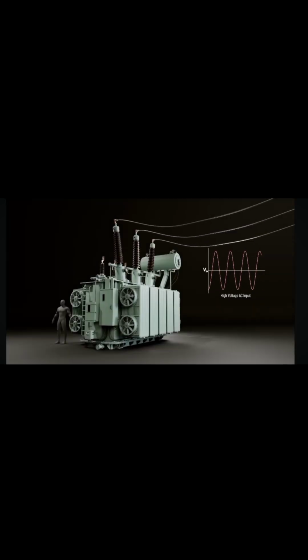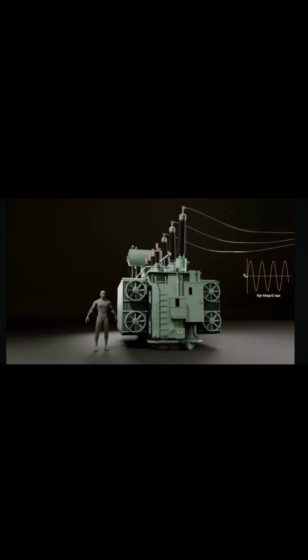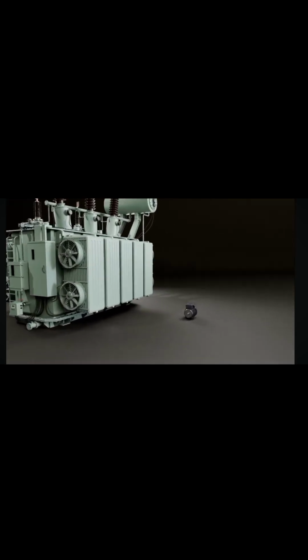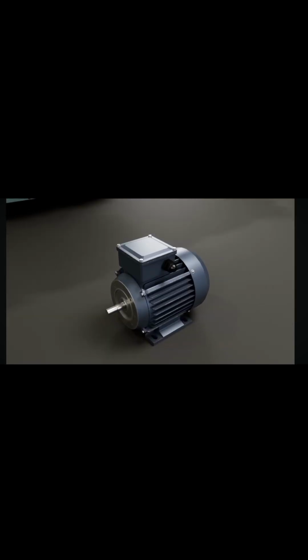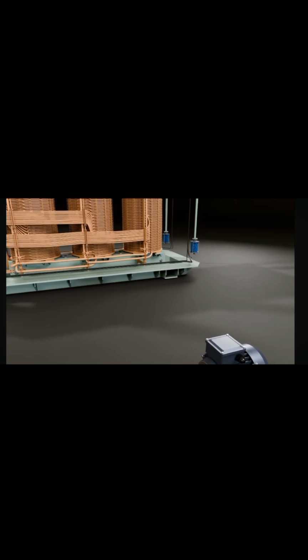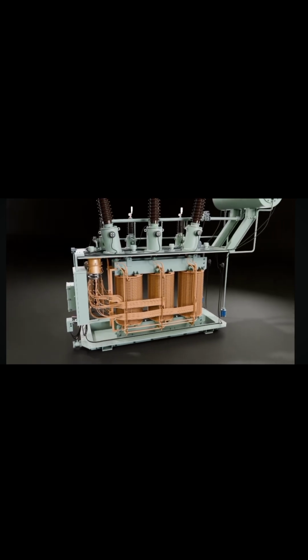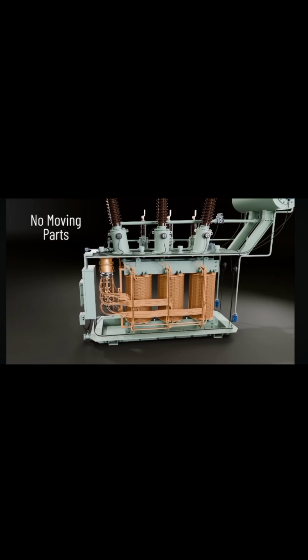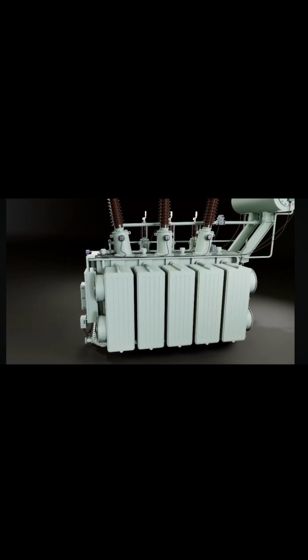A transformer is used for increasing or decreasing the voltage levels of an AC supply, with a corresponding increase or decrease in current. It is a static machine, which means, unlike an electric motor, which has a stationary part called the stator and a moving part known as the rotor, a transformer does not have any moving parts, except for the OLTC and motor drive unit, which we will discuss later in this video.